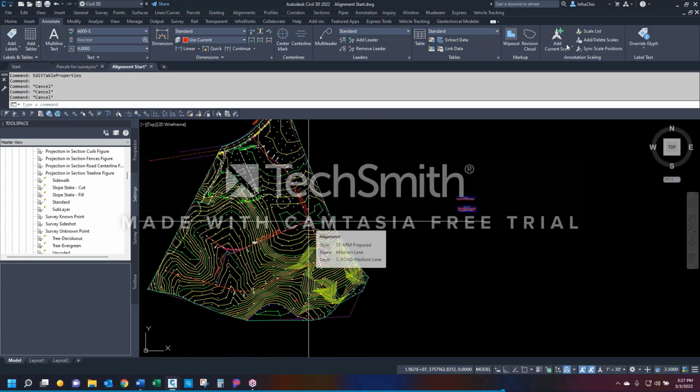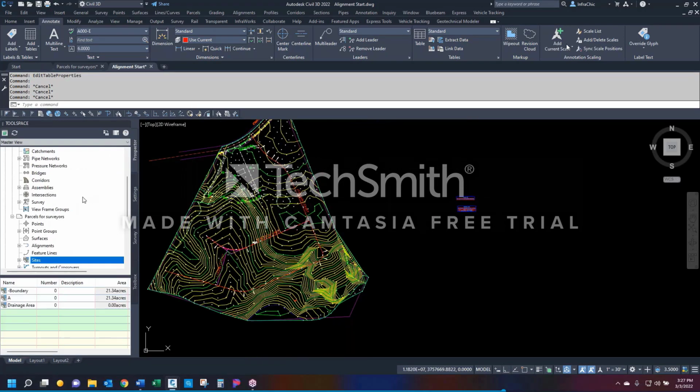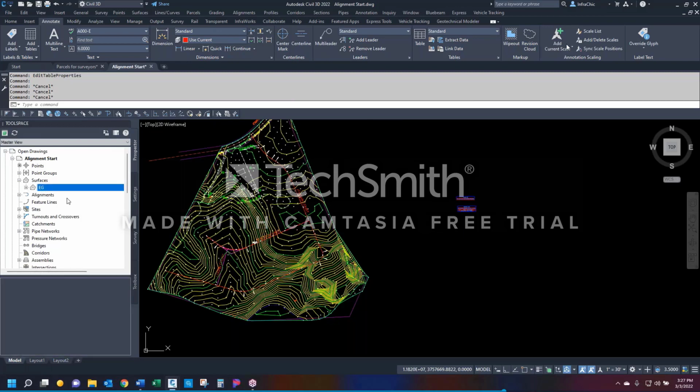Now we need to talk about profiling. Profiling, once an alignment's been made, is very simple. Number one, to profile, you need to have a surface in your file. We have the existing ground surface in our file. Yay. No surface to start, no profile ever is made. That is the rule of thumb. It has to have something to sample from just to get something created.